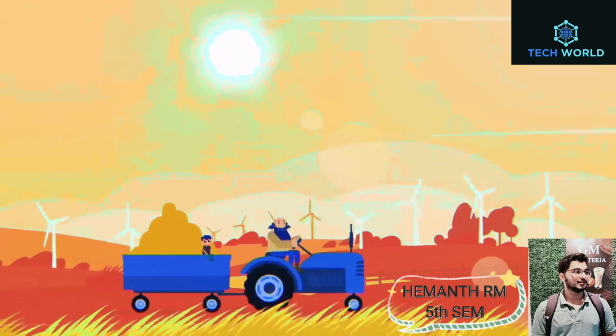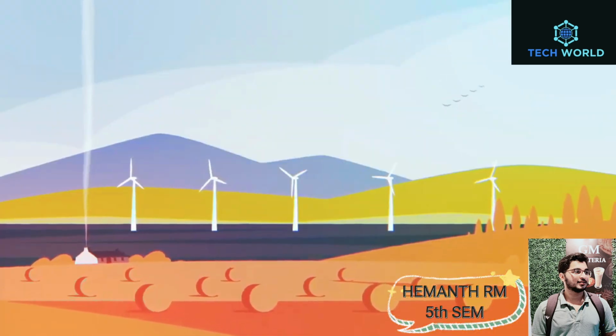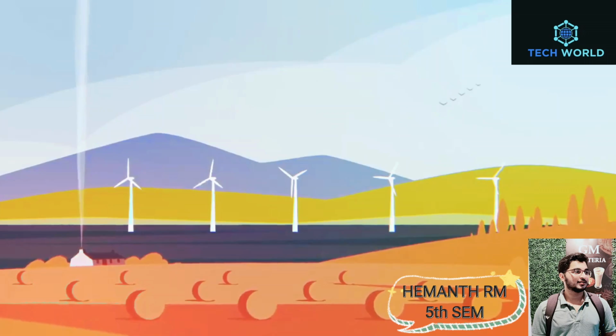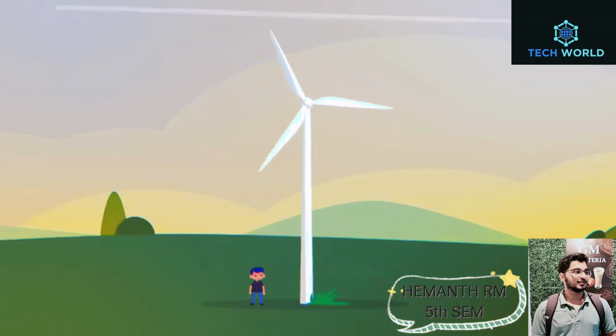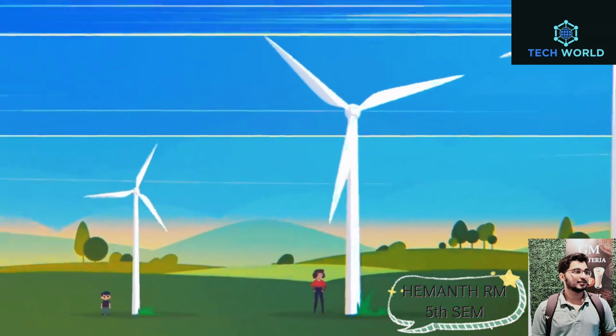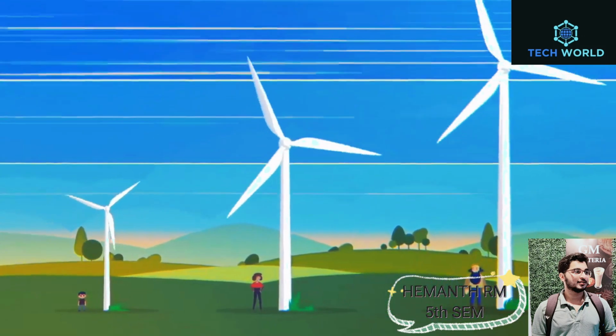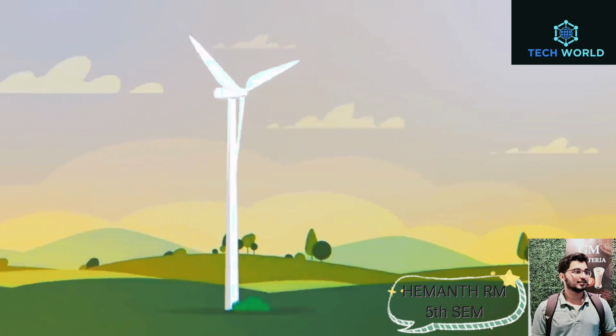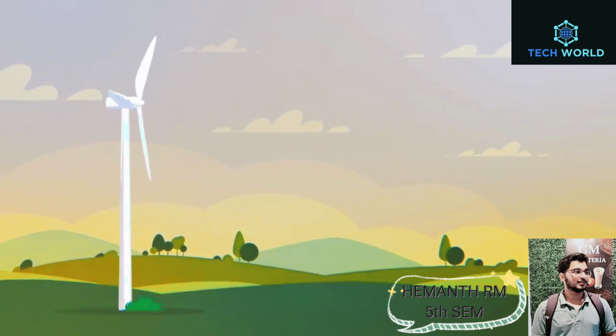Since the amount of lift depends on the angle at which the wind moves relative to the blades, modern blades also incorporate a twist, optimizing how much the blade can cut into the wind. They are made of fiberglass and precision layering. These blades are strong and designed to operate through lightning and blazing sunlight for over 20 years.